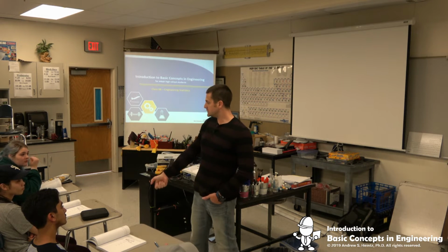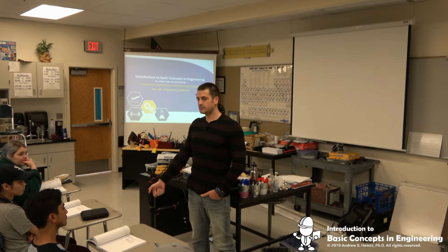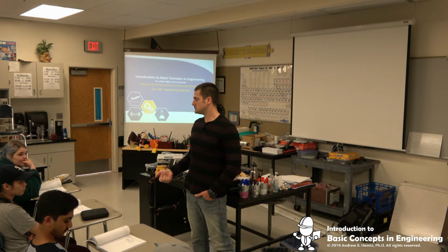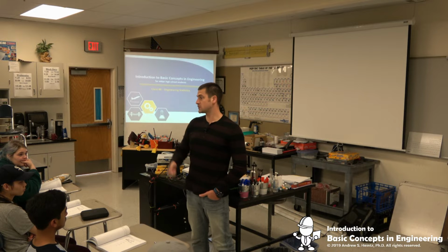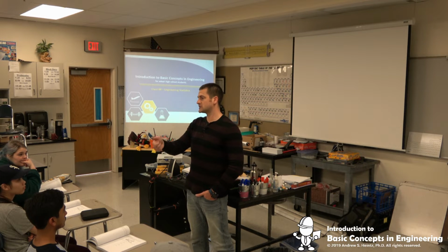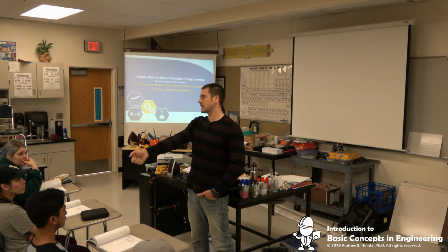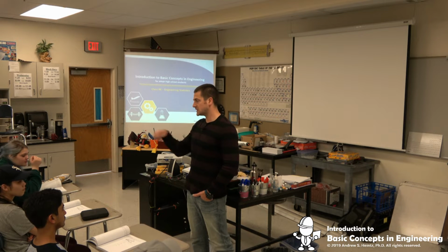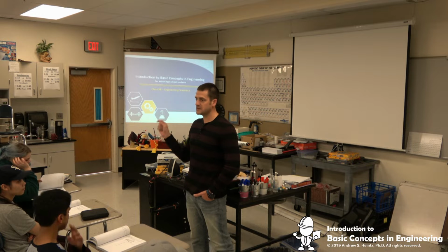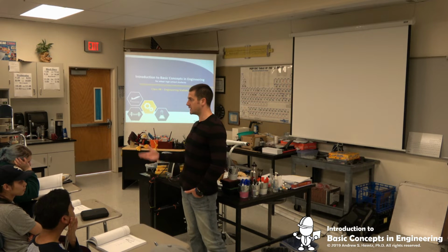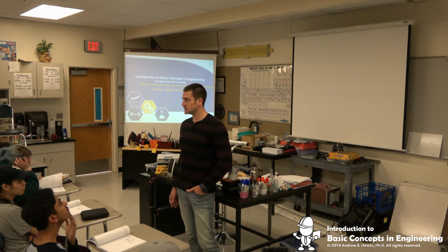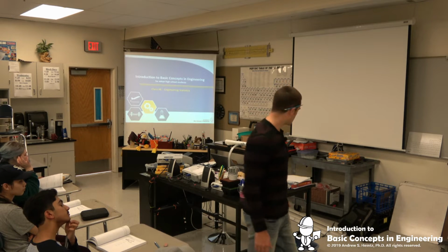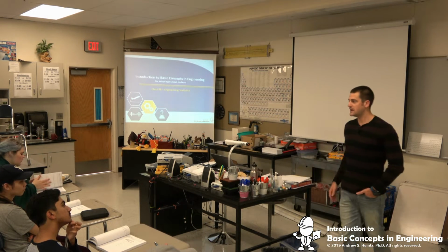If you're covering the hose with your thumb, are we creating more pressure? You're not creating less pressure, but when it comes out, you're creating less area and the liquid has to speed up. That's why you've now given kinetic energy to those little water molecules. They can knock the grass off the pavement or the gunk off the dishes or whatever you're trying to do. Do we have any questions on that?